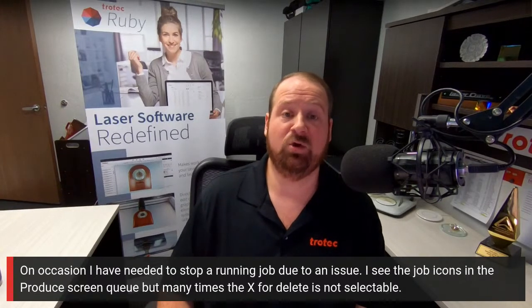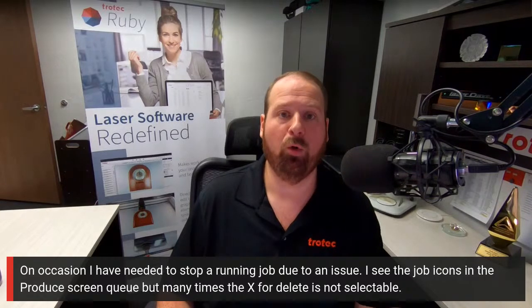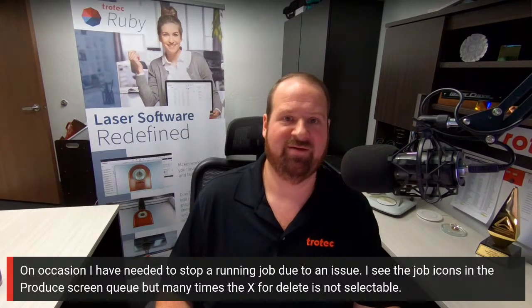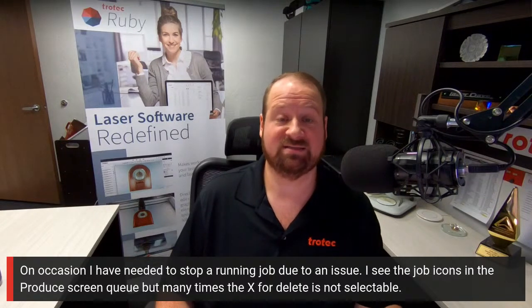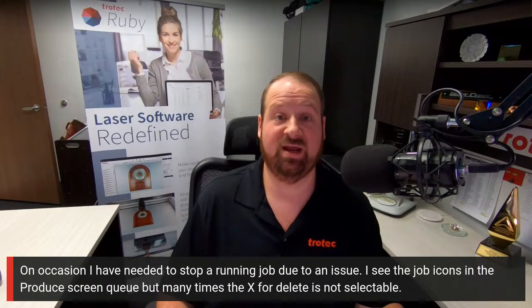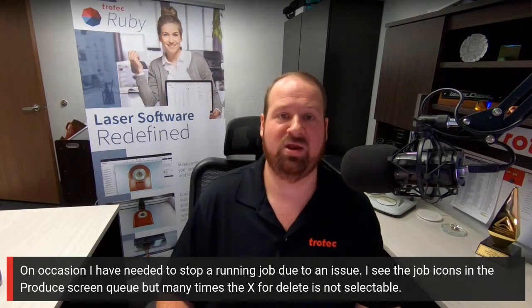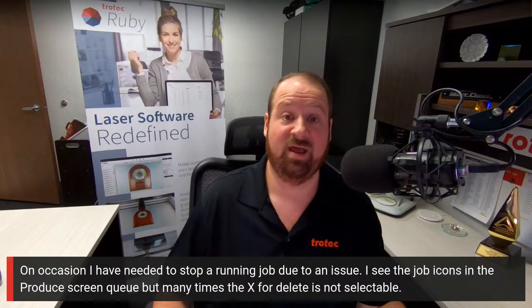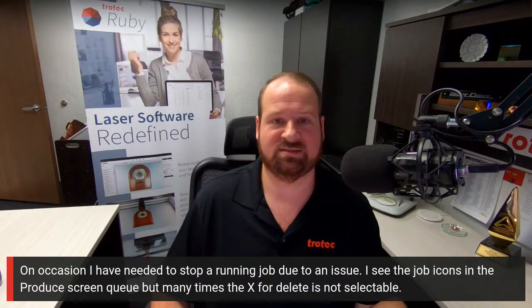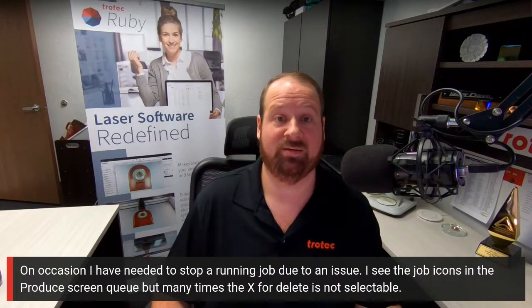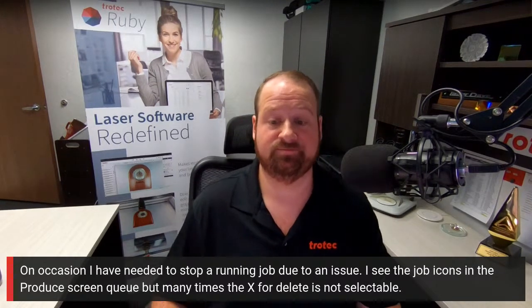The one thing that I do, if you want to guarantee it stops, is click and hold the stop button on your laser machine for 5 to 10 seconds. This will force it to stop. Once it has stopped, you're usually going to hear a beep on your laser machine, and then you can go into your menu and delete those jobs. In essence, if you stopped it, paused it, or lifted the lid, the laser sees it as a paused job, and because it's paused, it's not going to allow you to delete it. So make sure you hit the stop button, hold it for 10 seconds if necessary until it beeps, and then you're going to have access to delete those jobs.